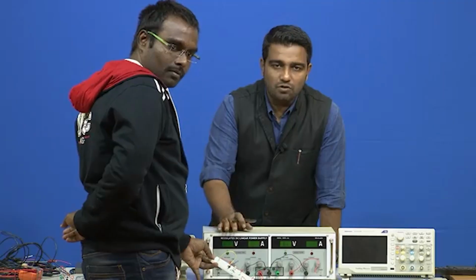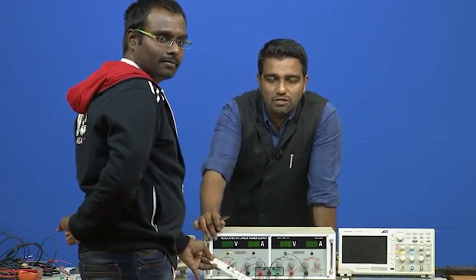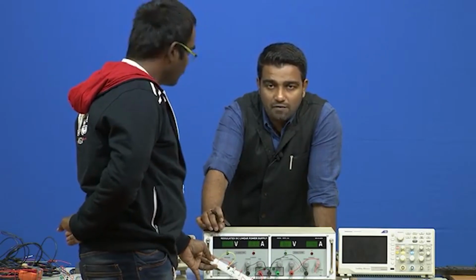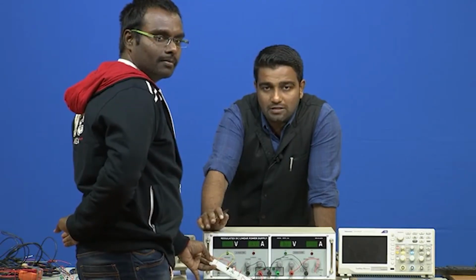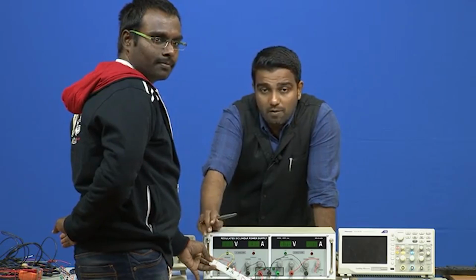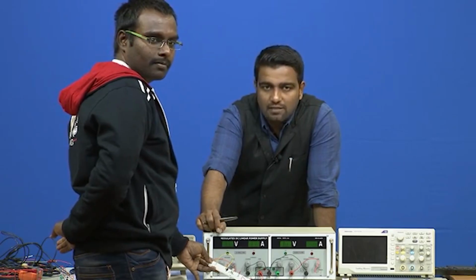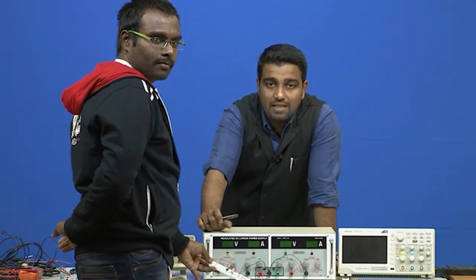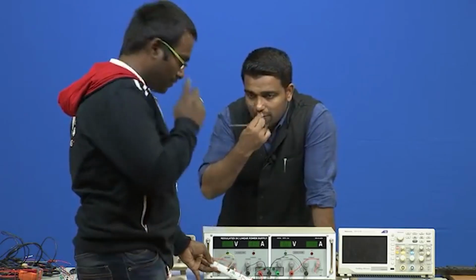So, instead of this potentiometer, we can directly apply through this DC power supply, right. If you apply 0, 1, 2, 3, you will see at a point when it is greater than 2.5 volts, we will be able to see the glow in the LED, and we will measure the voltage across the potential divider initially, then we will increase the voltage and then we will see what is the output, alright. So, let us perform the experiment.